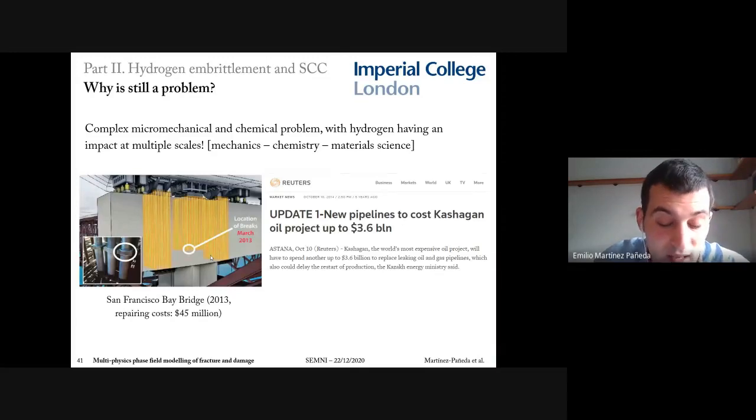There are some cases where you can design some hydrogen-resistant materials. So we know, for example, that there are some microstructural traps that will basically retain the hydrogen and will not allow the hydrogen to diffuse to the fractured region. So in some applications where you have a limited amount of hydrogen, it is possible to develop this sort of materials that will be able to take in more hydrogen without releasing it to the fractured region.